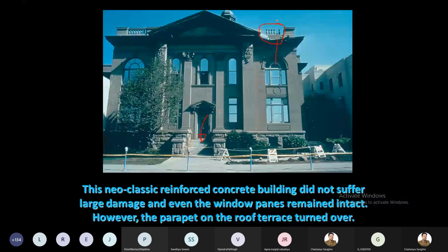So what is the ideal way? Ideal way means you have to take the slab reinforcement and then construct a parapet using RCC, and the slab and the parapet should be connected so that during the lateral force no failure will take place, right? Then the next part is liquefaction. Now what is liquefaction?